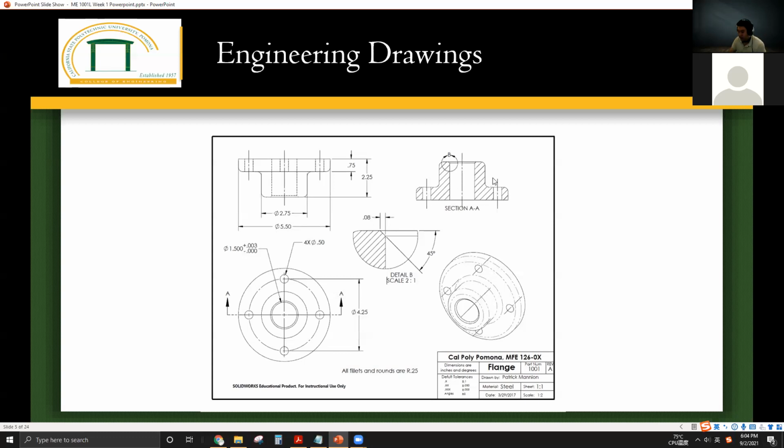The section view is for the cross section, and the cross section is labeled A-A. From this view you can see the leader line and the line that cuts through the cross section, also called A and A. So when you see something like this, you go to another view to look for the section, and this is the line they follow to cut the subject in half and show you what's inside of it.